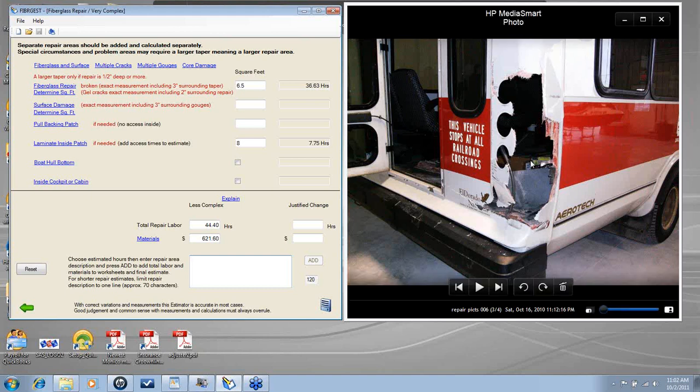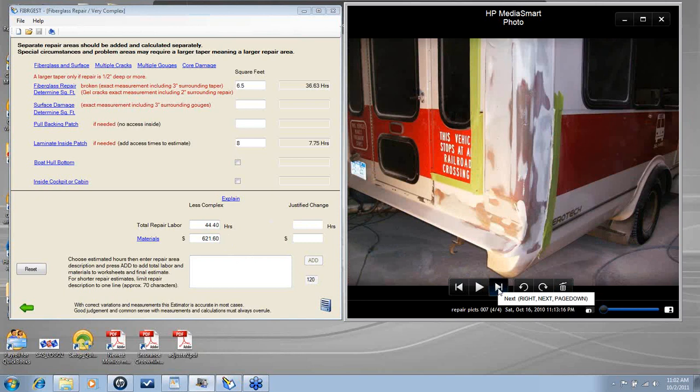So it takes a lot of repair hours to repair that, and that's why this came in at such high hours to repair that. I can show you a picture here after it was ground, laminated, and starting to straighten it, and you can see it's all laminate, but just a slight bit of filler to fill your slight lows and your pinholes. But it is all laminate and just a very thin layer of filler just to, like I said, fill those pinholes and slight lows.